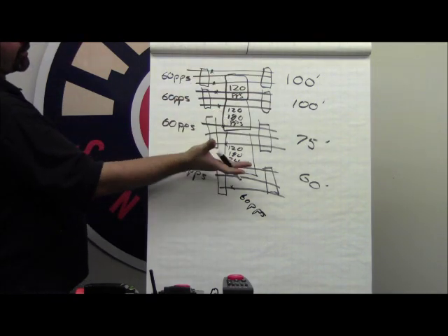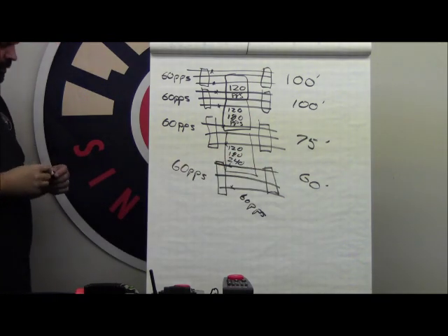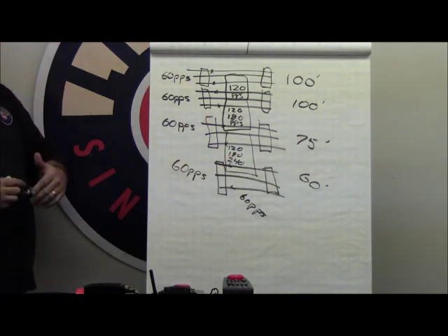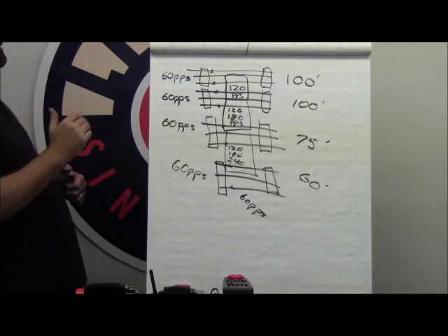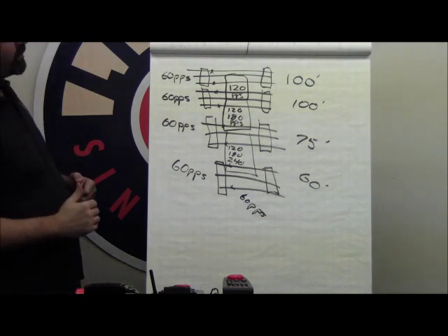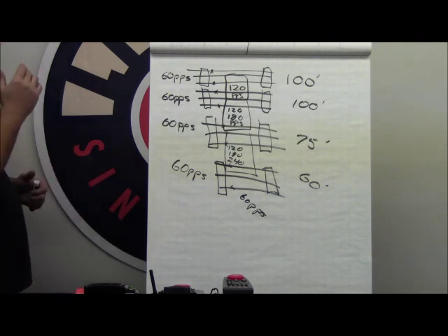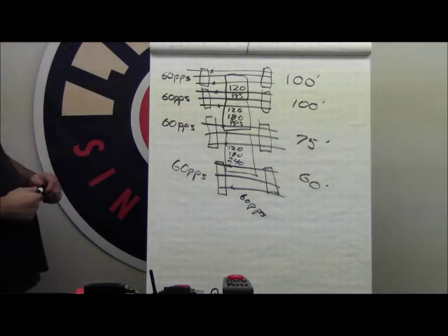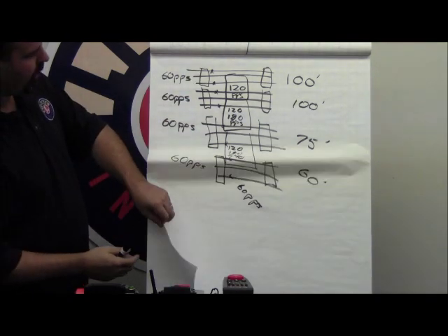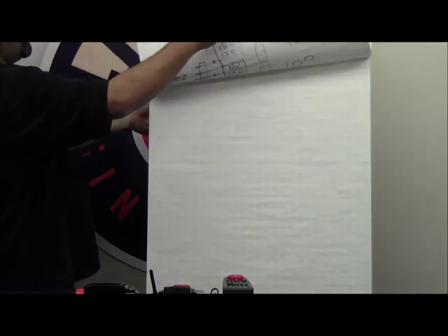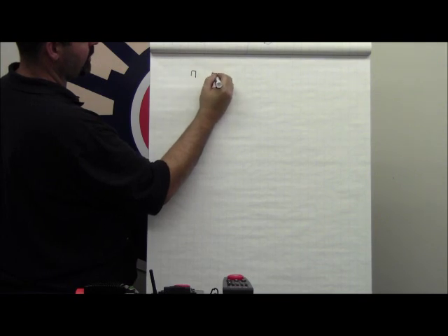So what ends up happening in this area is whenever you run a train through any of these tracks, you could have a potential where the headlights flicker and the engine loses its command signal. This happens because of this crosstalk of the signal. It's very rarely, if ever, an instance of not having enough signal, but rather having too much signal. And the way to solve these problems is with that ground plane. And in an instance such as this, where we have 4 parallel tracks, the easiest way to solve that with a ground plane is as follows.